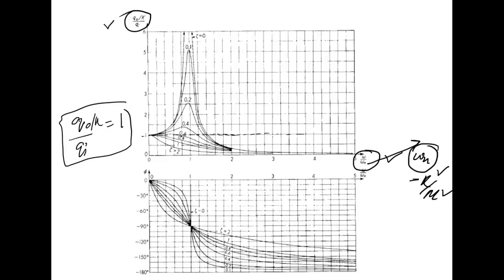But at the same time, we have to be careful about the damping ratio also. So if we keep zeta equal to 0, we will have huge amplification, which is almost a resonance, where the frequency of the forcing function is equal to the natural frequency of the system, so it resonates, and we can have very high amplitude, which is again undesirable. So we would like to keep zeta around 0.6 to 0.8, where it almost follows a flat curve here, and then keeping omega n very high, so that this whole ratio is less than 1. So this is what we would like the instrument to be designed for.